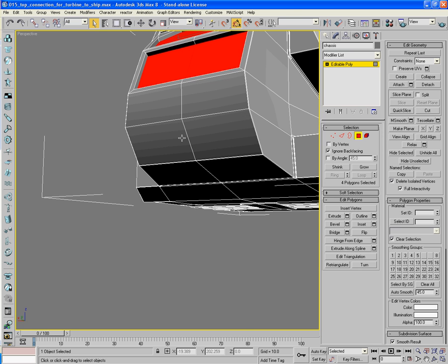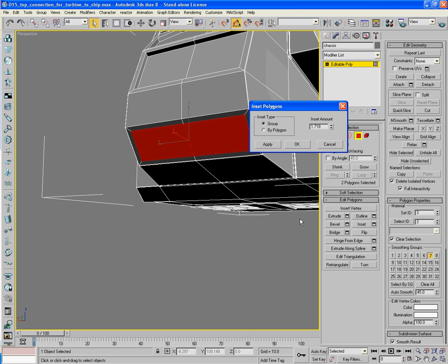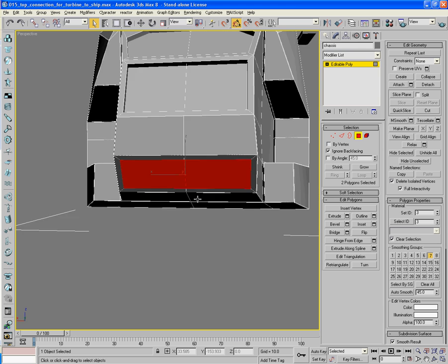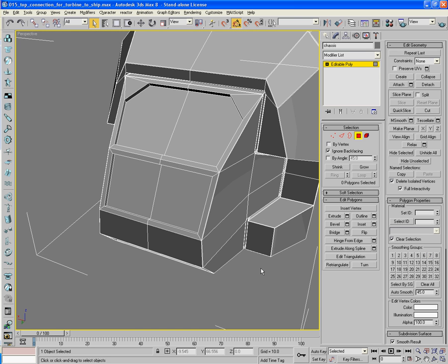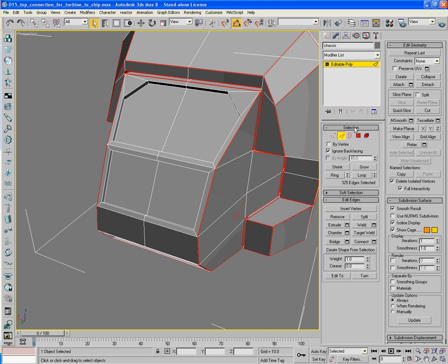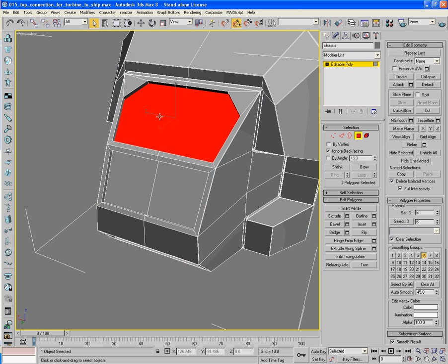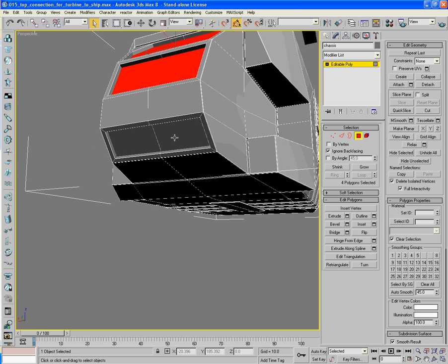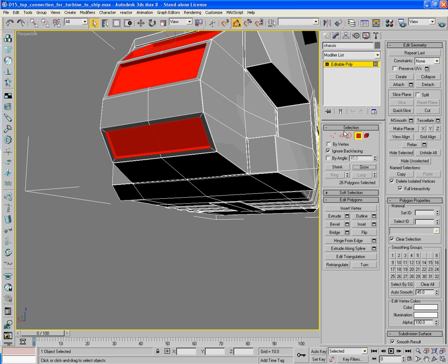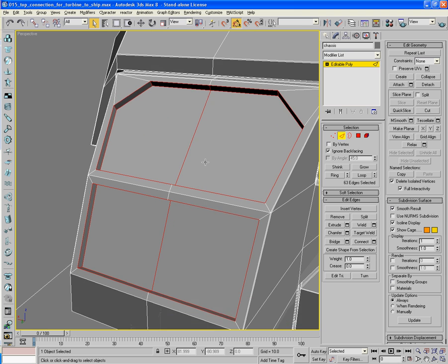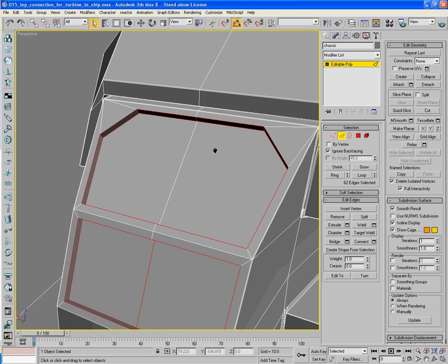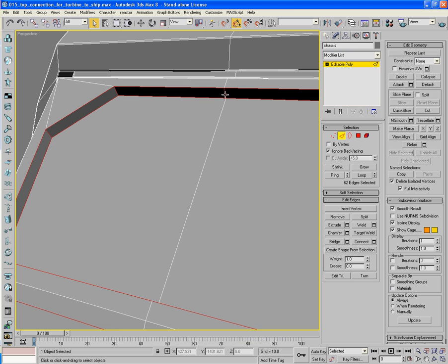And then down here at the bottom, nice little inset there, and extrude them in. Again, we're still just making the basic shape here, we haven't even got to the detailing of these parts. Next, just to chamfer these fellas out. I'm just going to click Grow and Control Select by Edge. I'm just going to remove the parts I don't want to do.